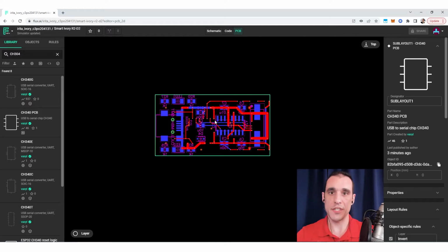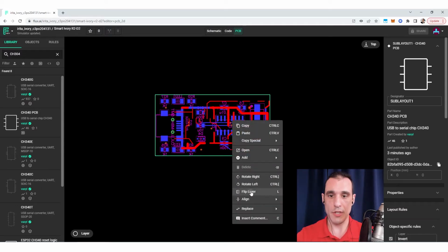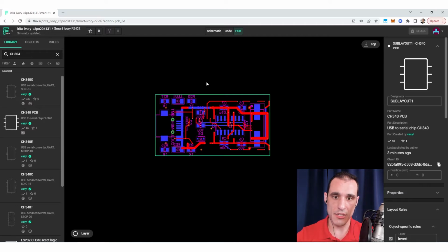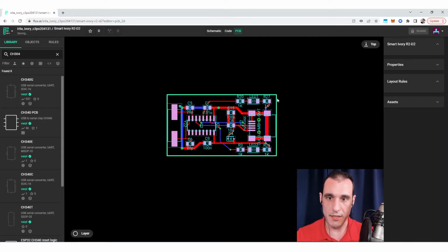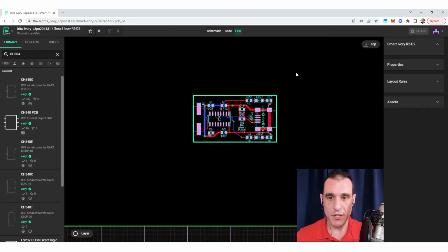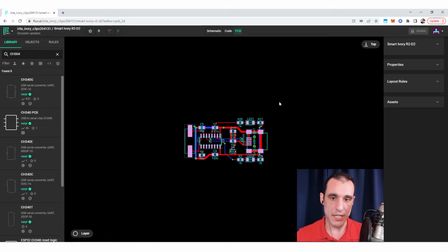I think it's important when you're first designing a sublayout to consider where you're going to put those components. Single-sided placement might be advantageous because it leaves you some room to access all of those available connections in the sublayout through the back layer. All you would then need to do is ensure that there's just enough room for vias, or that you place the vias inside the sublayout. And so that's what's going to allow you to access any of those connections on the opposite layer just using the standard routing tools inside Flux. So make sure you think ahead a little bit and decide where you need to put components, either on a single side or on a double side.